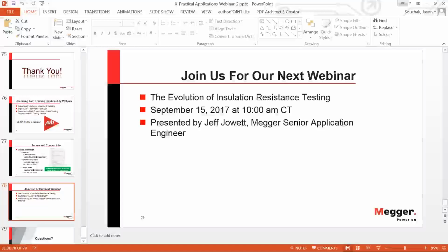Thank you, Jason. Henning, do you have anything to add to that? Yeah, in terms of tan delta testing, I don't know exactly the number, but it's in the few nanofarad range that you must have as minimum cable capacitance in order to measure tan delta. You don't need microfarads, but you need something in the nanofarad area, I think maybe 8, 10 nanofarads. It's specified, and different manufacturers have slightly different levels there, as a minimum capacitance, which translates into a minimum cable length in order to do tan delta testing.